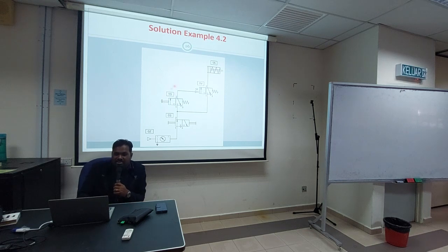Okay. So you boleh tengok how the circuit is designed using indirect method. So yang ni 0Z dengan 0S safety. So you ada push button dekat sini. So dia masuk ke the 3/2 valve and it will be connected to your cylinder. So you press the push button, yang ni dia akan ubah ke initial position. So it will give input to the cylinder and it will activate the cylinder. So you lepas yang ni, so because of the spring, dia akan pindah balik ke your normal position and it will disconnect this, and because of disconnection, your cylinder akan retract balik.